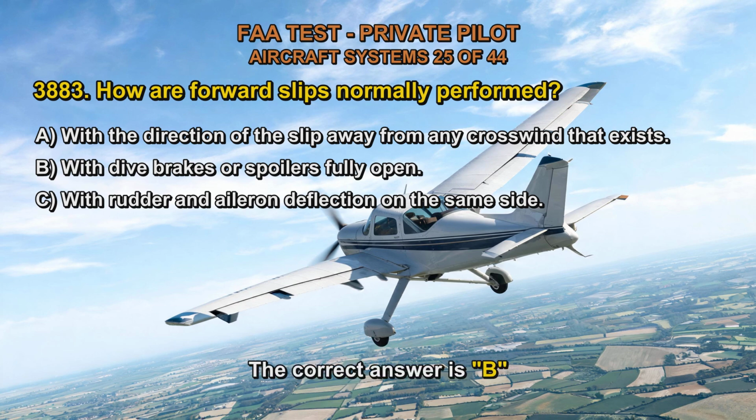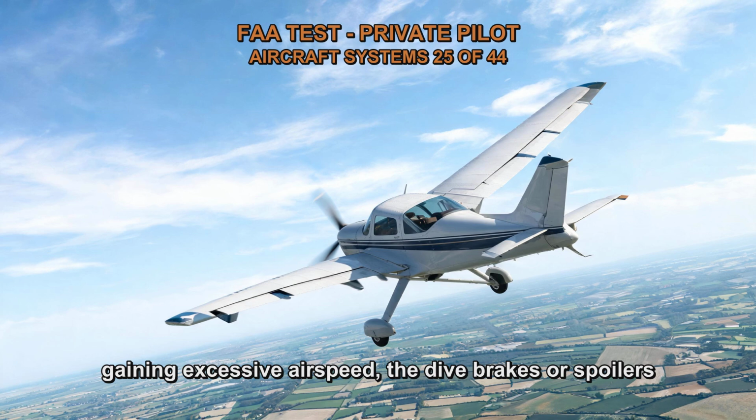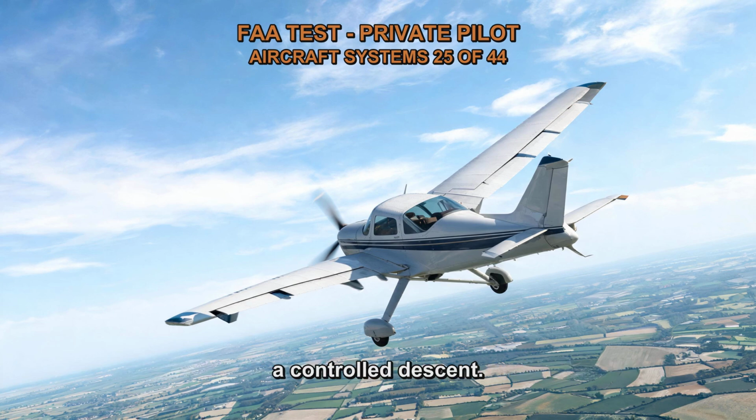The correct answer is B. During a forward slip maneuver, where the objective is to increase the angle of descent without gaining excessive airspeed, the dive brakes or spoilers are typically fully extended or open. By deploying the dive brakes or spoilers, the pilot increases the drag on the aircraft, which helps to counteract the forward motion and maintain a controlled descent.